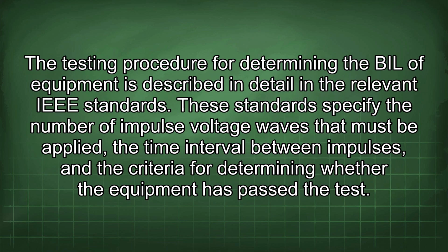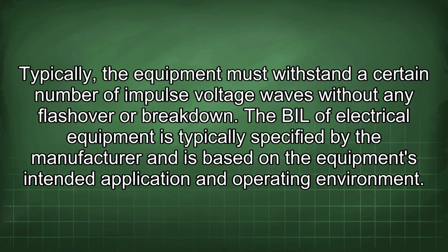The testing procedure for determining the BIL of equipment is described in detail in the relevant IEEE standards. These standards specify the number of impulse voltage waves that must be applied, the time interval between impulses, and the criteria for determining whether the equipment has passed the test. Typically, the equipment must withstand a certain number of impulse voltage waves without any flashover or breakdown.